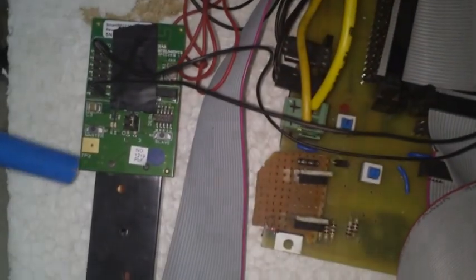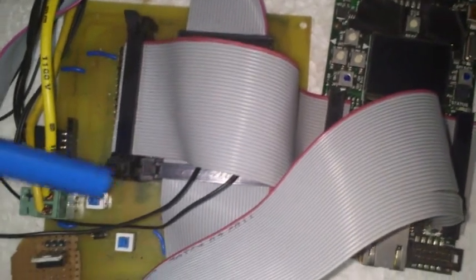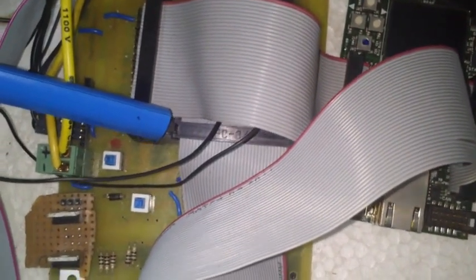The server computer is connected to the client computer through the network. The client computer receives the data and transmits it to the RF module through the RS-232 jack. The receiver RF on the robot side receives the data and sends the same through a PCB board to the arm. The PCB board is powered using various voltage regulators such as TL783, UA7805 and UA7806.